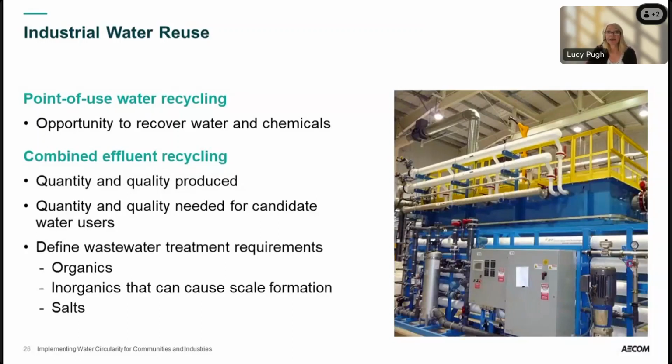And here again, we need to understand the characteristics beyond what might be monitored for effluent discharge. So a complete ion balance, anions, cations, other constituents that may be present, may not be normally monitored for, but we need to have an understanding of everything that's in that effluent so we can evaluate the impact on the water reuse.